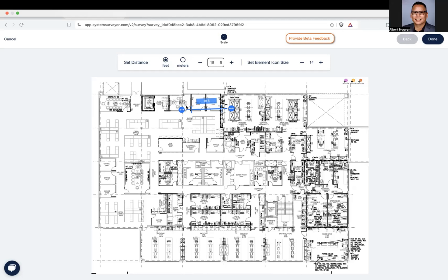Sorry about that. I was just asking because sometimes I get these drawings and I rule up to scale, and sometimes they're really huge. I was wondering if I just mark the door at 3 feet, just to get some kind of measurement. If that's 3 feet, can I enter 3 feet and just scale the whole drawing? Yes, sir. Okay. You can use the plus or minus, that sort of thing too.